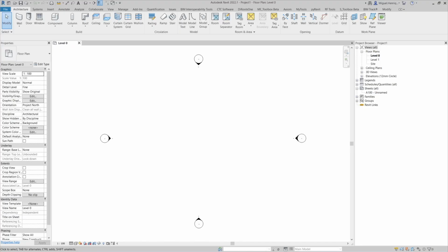Now we can go to Revit. In this case, I am just working in the default architectural template. So there is nothing here. It's just a placeholder to show you. So in the level 0, you can pick any level really, but I like to create a level 0 and then a level corresponding to the altitude or the level of my Civil 3D model. In this case, I will just work on level 0.